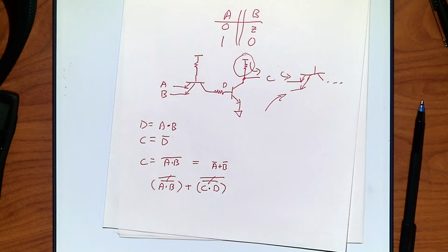What would a three-input gate be? How much current would I have? Three inputs, potentially. See where I can start building up pretty crazy, pretty quick here? Pretty soon you're going to get a ridiculous amount of current flowing in as you start adding more and more gates. And do we want more gates than just two? Well, it'd be nice. Think about some of the logic you've built. If I were building some large, complicated circuit, and I could have a 4, an 8, or a 16 input AND gate, that could help me calculate some things fairly quickly without cascading a bunch of logic.